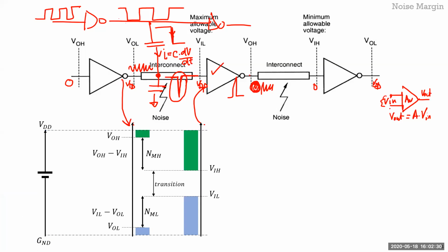So I've divided this whole range from VDD to ground. That's your supply, right? Any voltage inside the chip, unless you have an inductor or some switched capacitor circuit, is not swinging above or below this. There's some ringing and swinging that happens, but for practical purposes, for the static case at least, without any capacitors.